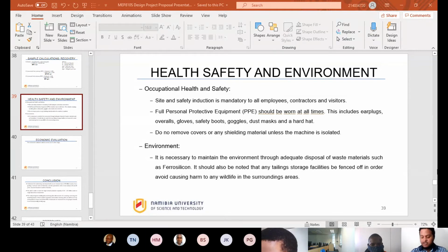So what I can say with regards to the dense medium separation circuit is that there are different floors and different sections in the dense medium separation circuit. In typical operations, on each floor there's, how should I say, a drainage system. So there are holes in the floors that lead to pipes, and those basically feed any spillages of, let's say, ferrosilicon. That would then lead back to the correct medium circuit.